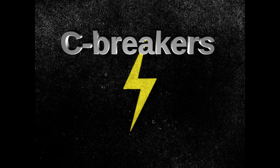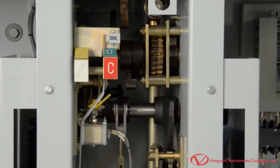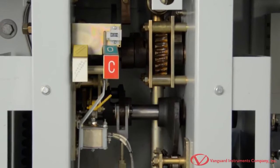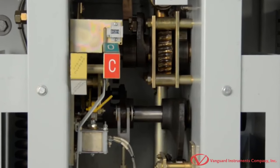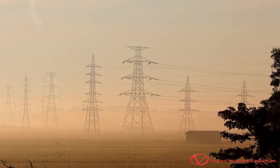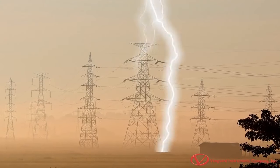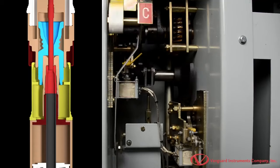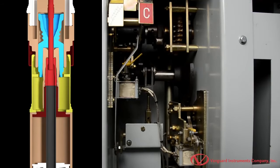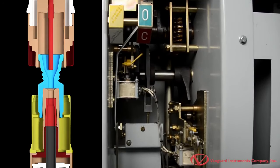Circuit breaker. They are mechanical switching devices capable of making, carrying and breaking current in normal and abnormal conditions. During abnormal conditions, such as when lightning strikes on the transmission tower, circuit breakers isolate the faulty components of the system to prevent additional damage. Ideally, in closed position, a circuit breaker should work as a perfect conductor to ensure optimal current flow. In open position, circuit breakers should act as an insulator and be able to break the current instantaneously.